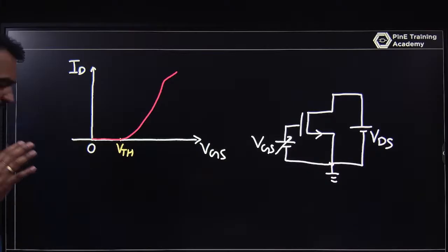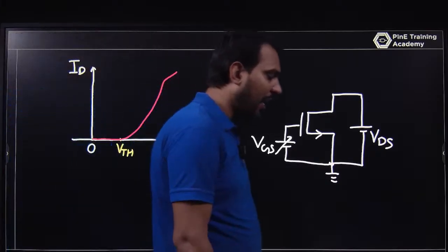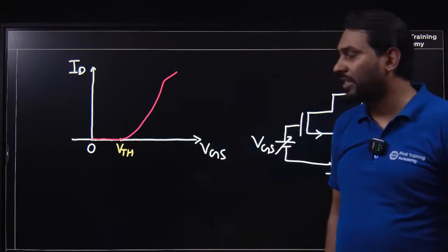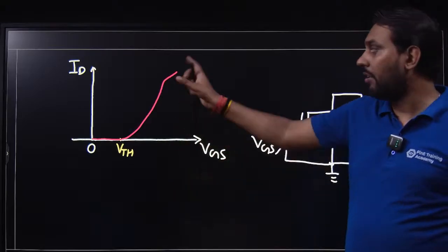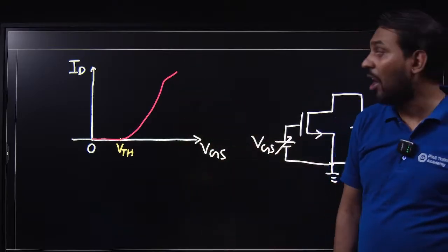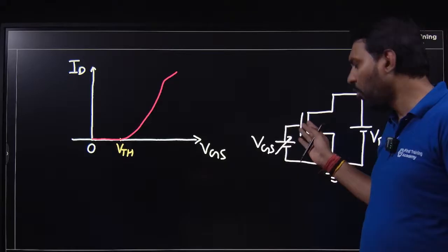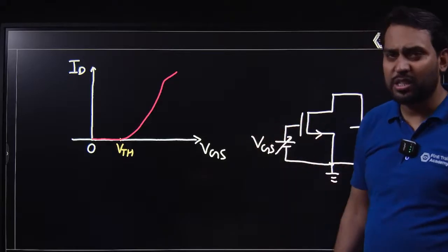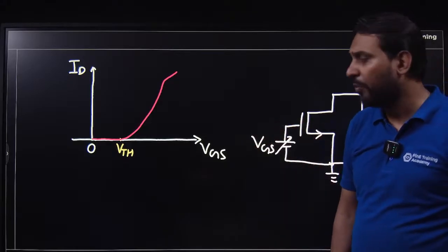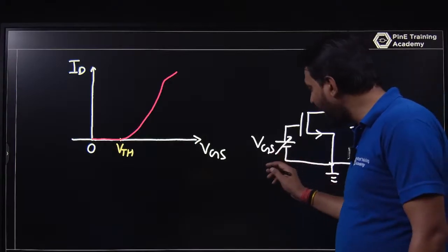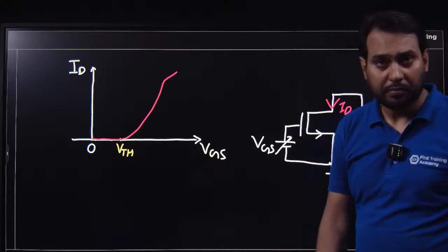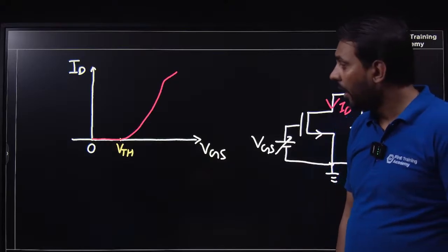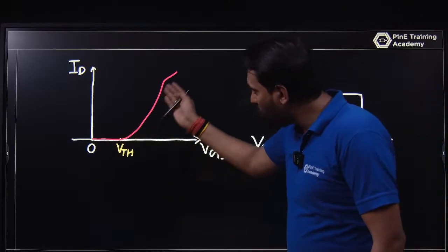They simply say, please draw an ID versus input voltage graph, where the input voltage is varying and you determine what the ID, the output current, is. Why not input current? Because the input current is 0, because the input impedance is infinite. So as per the tweaking of the gate to source voltage, you are focusing on the ID, the drain current. So that current looks like this.